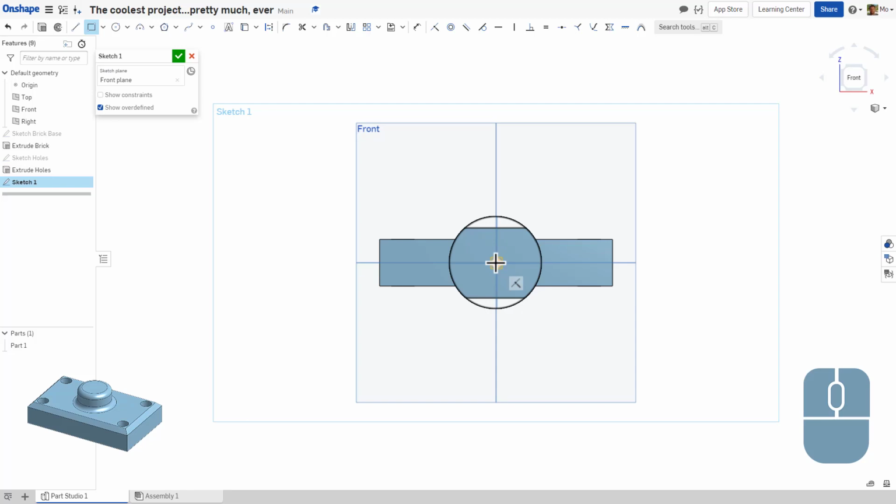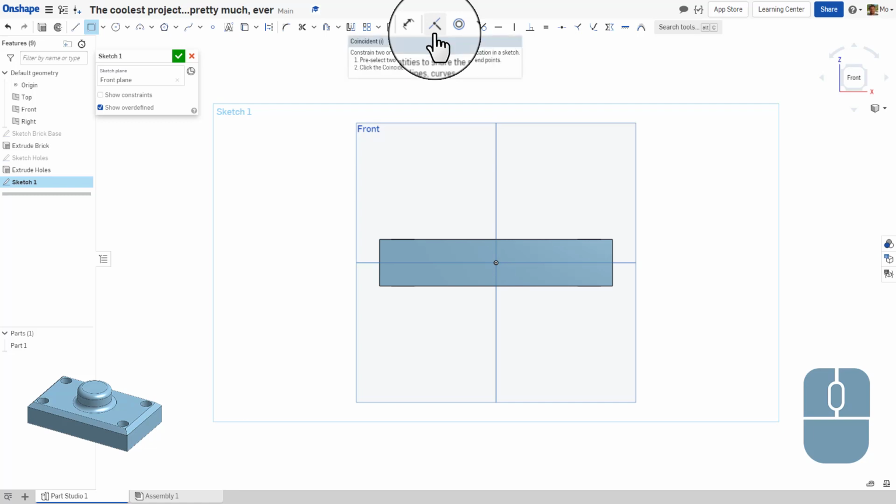Do you recognize that? Aha! The coincident constraint. And in fact, the horizontal and vertical constraints. What this is saying is that if I were to click right now, which I will, and I start to draw my rectangle, when I drop the second corner of the rectangle, you'll notice that the left and bottom edges of the rectangle are already black.